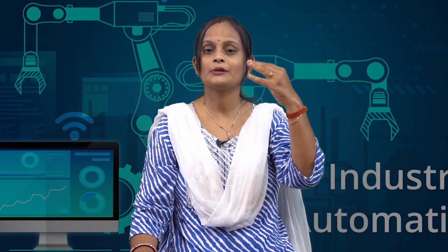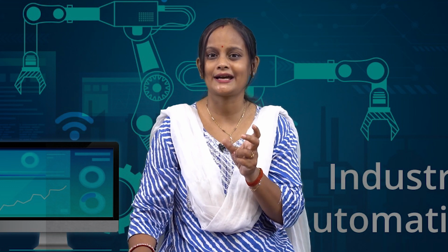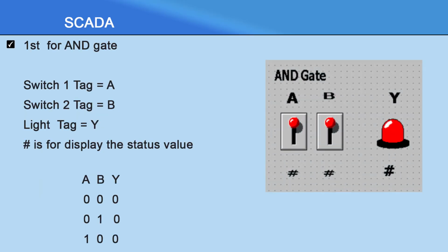Now we will see another example. You remember in lecture 37, I think I covered how you can write script programming or SCADA programming for logic gates. We used the AND tags expression there. Here we will also see how you can do it for the AND gate. Similarly I have used two switch buttons A and B, and an indicator Y. Switch 1 tag is A, switch 2 tag is B, and for the light we have used the tag Y.